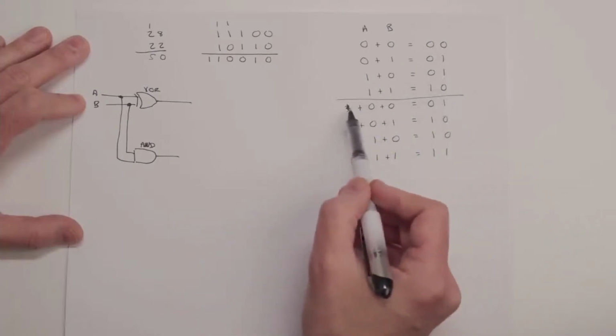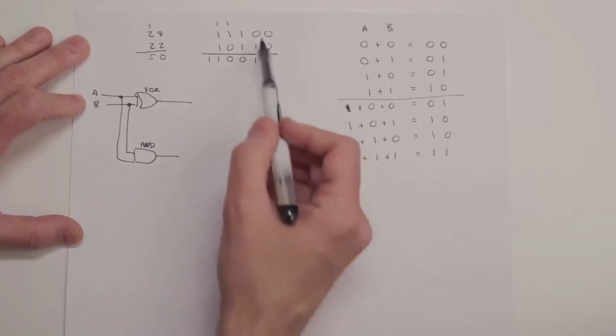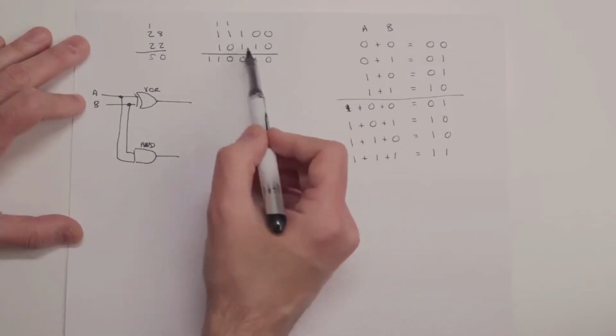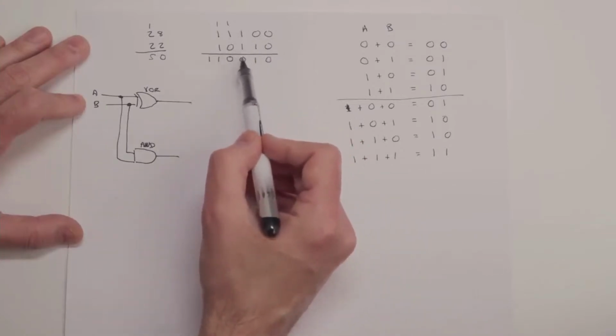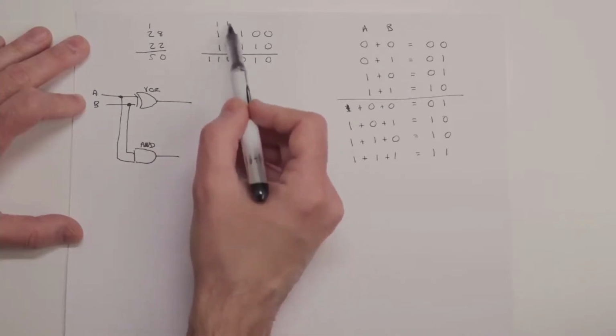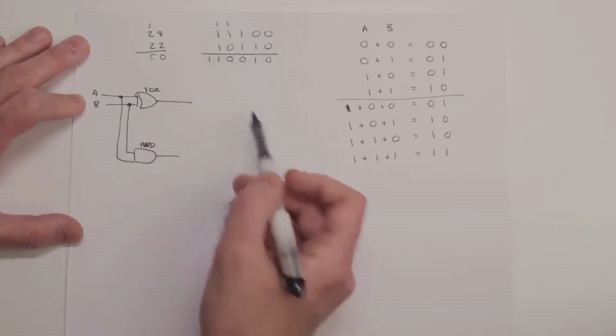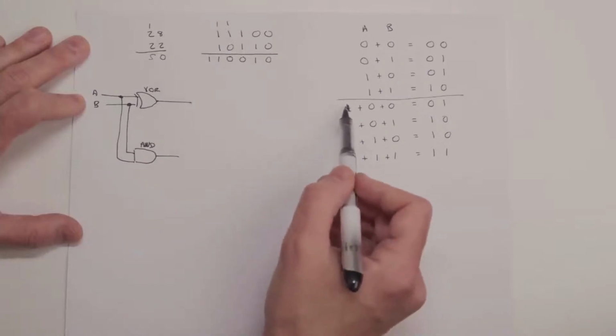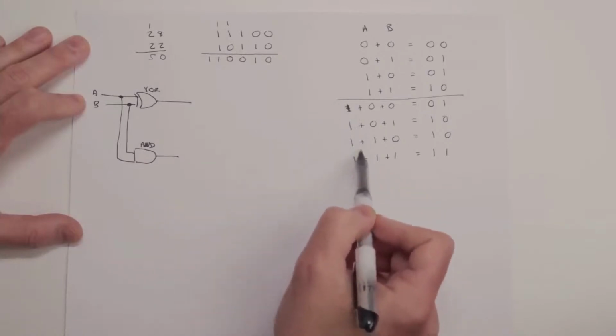It gets a little bit more complicated now if we have a carry coming in from a previous column, because it's not enough to just be able to add two digits, because as soon as we get to this 1 plus 1, then we have to carry a 1 to the next column, and in the next column we have to deal with three numbers. So let's just kind of add this case where we have this carry that might be a 1.